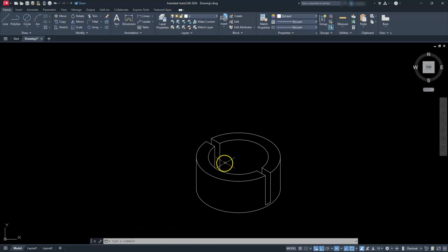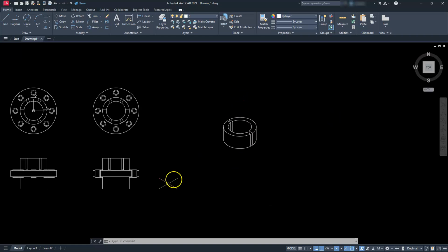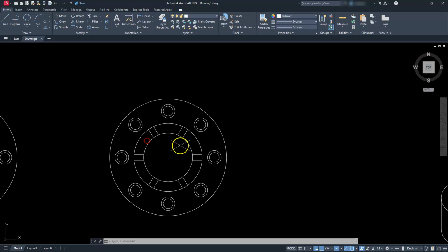Now I have 2 more lines that I do have to create. I have a line going this direction and one going that direction. In order for me to figure that out, I have to use some geometry. What I'm going to do is switch out of ISO draft. I'm going to draw a line from that center going to that quadrant. And now I need to put a line right in between here going up that direction, right? Well, we know the rotation of that.